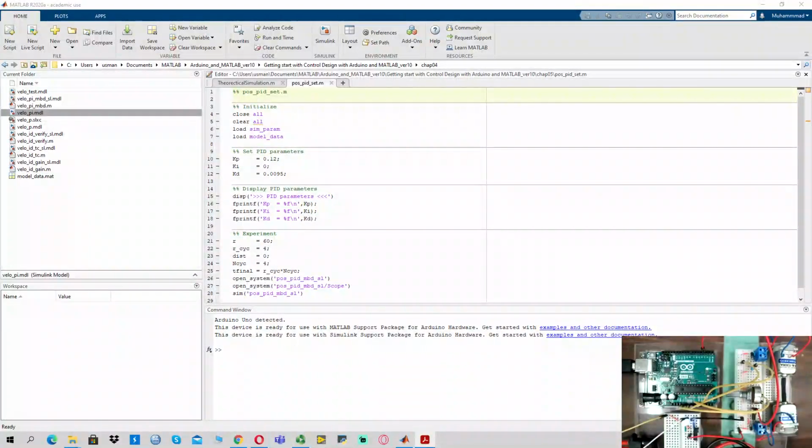If you look at the hardware setup, this motor is powered and the second motor is used as a tachometer, and this is the potentiometer that gives you the speed commands that you can see in the block diagram. We also have diodes to block the reverse current flow in the circuit, so as not to damage the Arduino. Then we have a FET right here, and the circuitry is pretty simple in this case. These are the two DC motors that we have used.